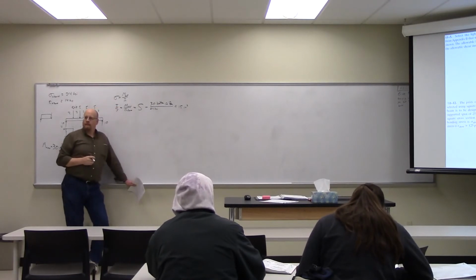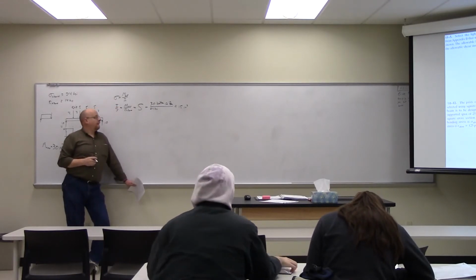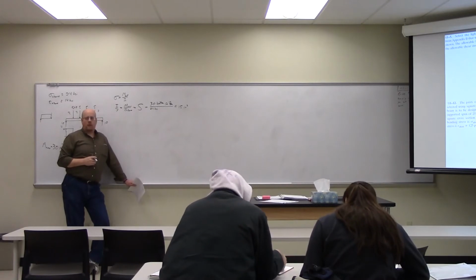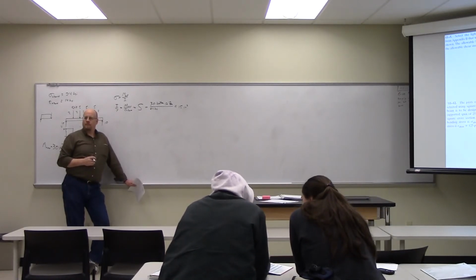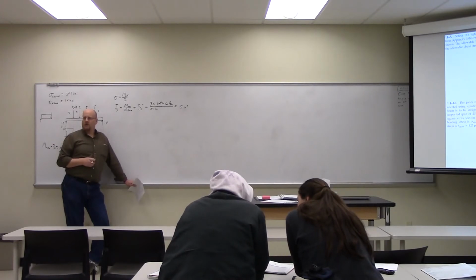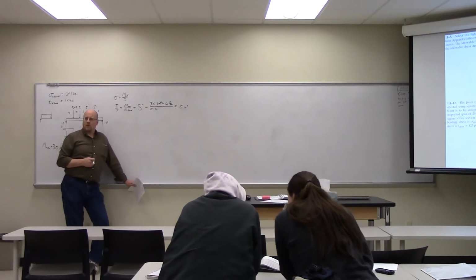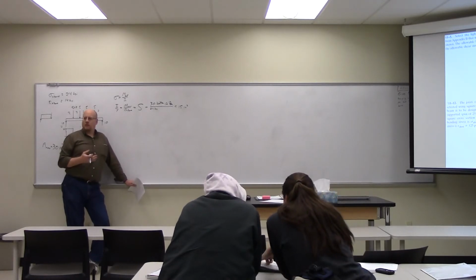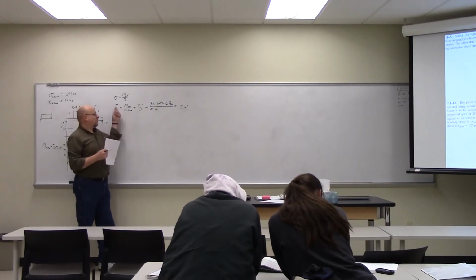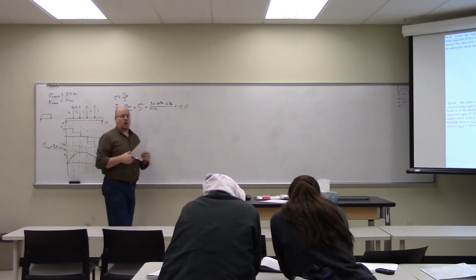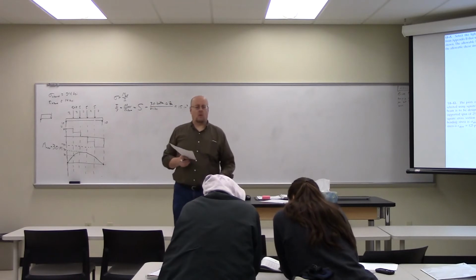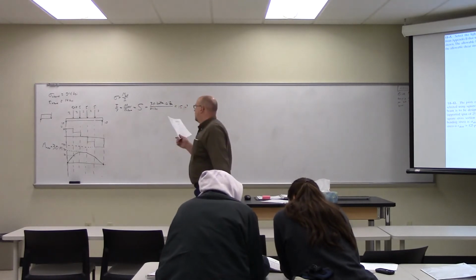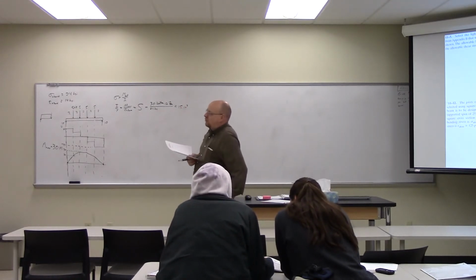Would you want to multiply by y, by the length of the beam? Nope. Why? We don't know what the height of the beam is. So now we want to go to our table, right? Because these I over Y values, the section moduli, are what specifically is calculated for us. So, do we want an S that's just less than 15 or just greater than 15?